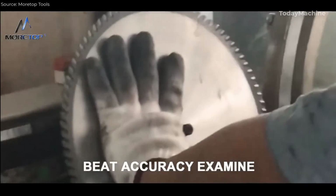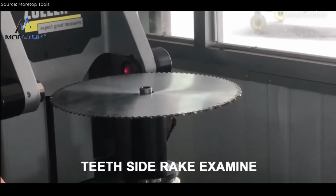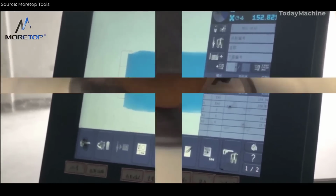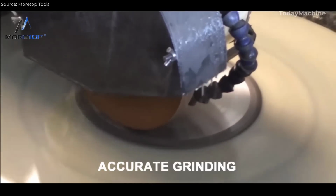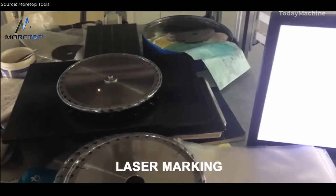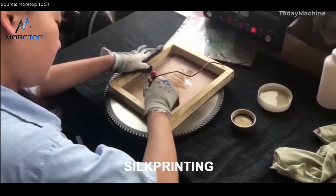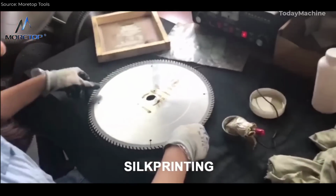Innovations in tooth geometry. Tooth geometry plays a critical role in the cutting performance of circular saw blades. Modern manufacturing techniques have allowed for the development of specialized tooth designs tailored for specific materials and cutting conditions. For example, triple chip grind (TCG) tooth configurations are now commonly used for cutting hard materials like aluminum and non-ferrous metals. These designs help to minimize material deformation and reduce the risk of blade wear, leading to smoother cuts and longer blade life.